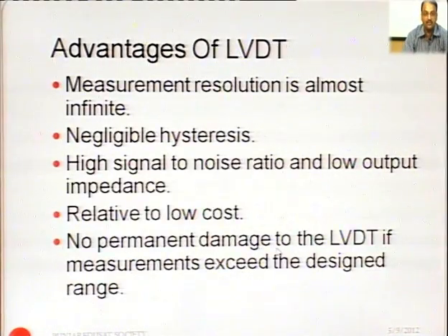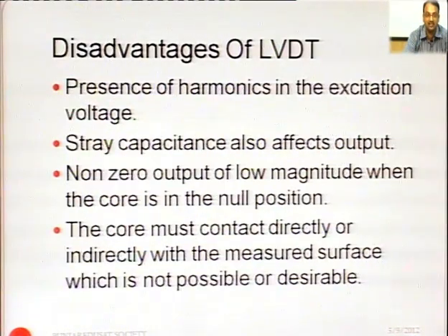Advantages of LVDT: their measurement resolution is almost infinite, negligible hysteresis, high signal to noise ratio, and low output impedance. They have very low cost. No permanent damage to LVDT if measurement exceeds the desired range.